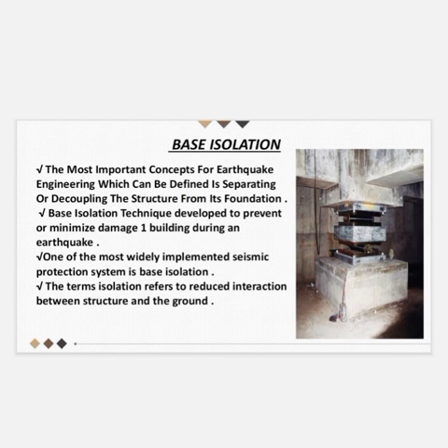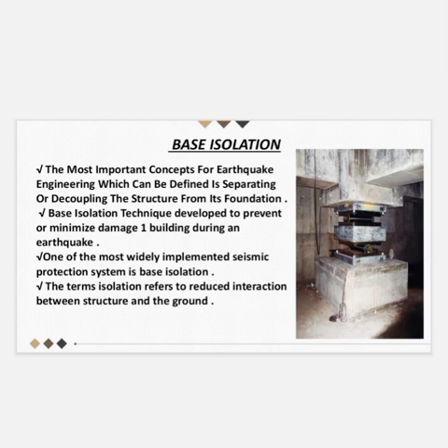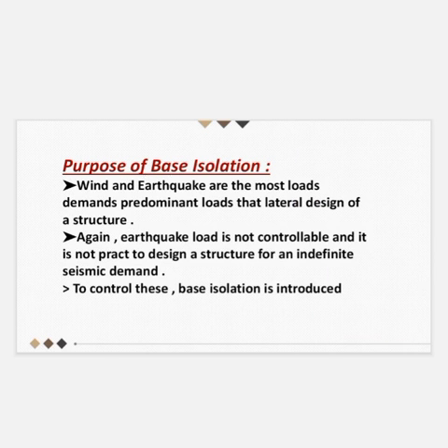The base isolation means the most important concept of earthquake engineering, which can be defined as separating or decoupling the structure from its foundation. The base isolation technique is developed to prevent or minimize the damage to a building during an earthquake. One of the most widely implemented seismic protection systems is base isolation. The term isolation refers to reducing the interaction between the structure and the ground.